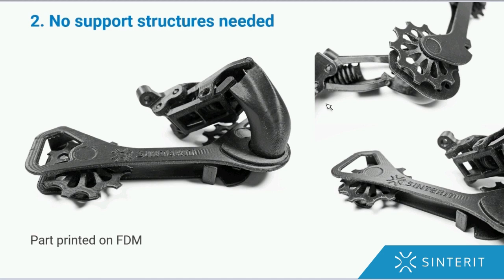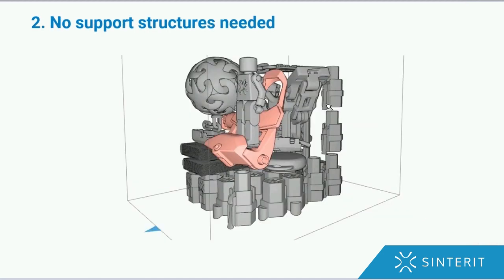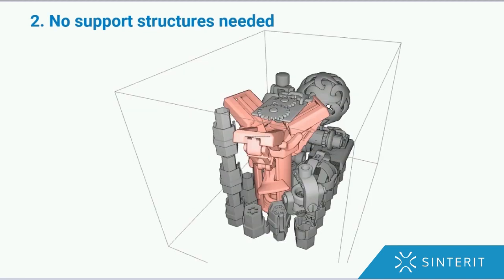No need for structural supports gives you another advantage. While using an SLS technique, you can print multiple objects at once. The process is called nesting, and let me show you how it works using this simple example. So as you can see here on this picture, you can print not only one layer of elements, but on top of that layer, you can print another one, and so on. So if you have elements positioned like this, they will still be printed.